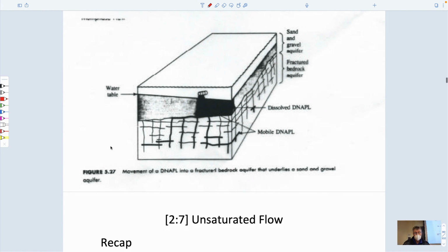Other than, we've talked about porous media so far, in which case we've talked about this layered architecture with a chimney that joins it. The problem is made much more difficult if you have fractured media, where the fluid will only travel within the individual fractures themselves, and therefore, one, it enters into the fractures very easily and can travel long distances laterally and vertically, and also the heterogeneity of these kinds of systems is much more difficult to characterize than a relatively homogeneous porous medium.